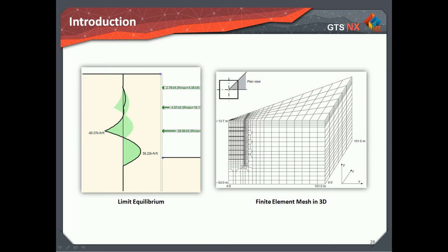Technically, full numerical analysis is the only method that satisfies all the theoretical requirements discussed earlier. It allows for realistic soil constitutive models, incorporates actual boundary conditions, represents the soil behavior with the correct geometry, allows for modeling the initial stress state, construction process and soil structure interaction, consolidation analysis, and so on.